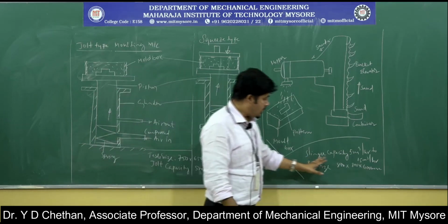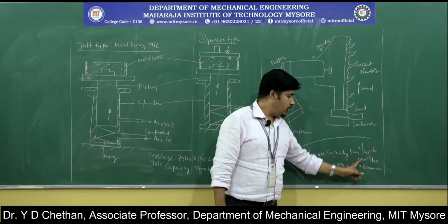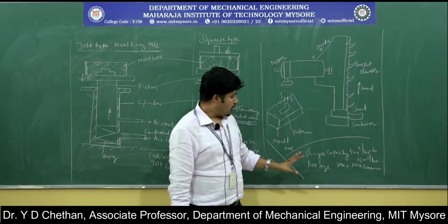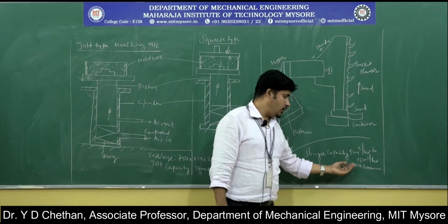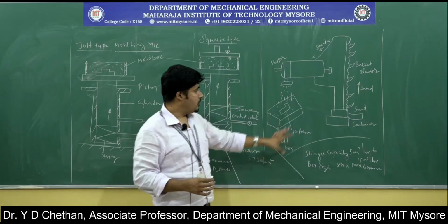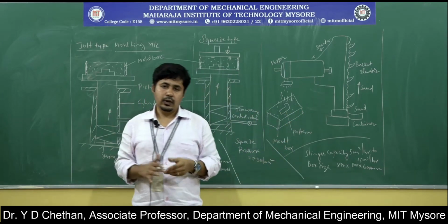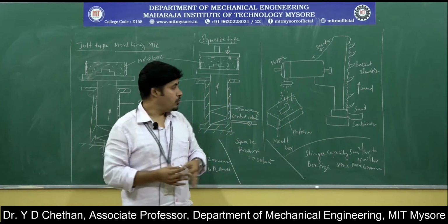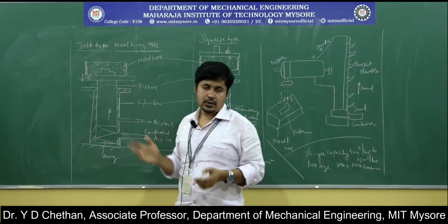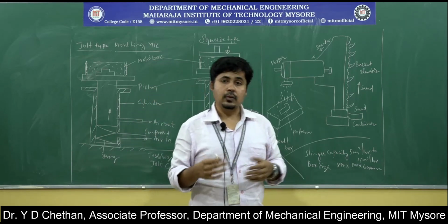The slinger capacity is about 5 cubic meters per hour to 15 cubic meters per hour. That is the capacity of the sand slinger. Then the box size is 800 x 800 x 600 millimeters. This is the specification of the sand slinger machine. If you want a mold with a very big volume, you can prefer the sand slinger machine instead of these two machines. This is the concept of different sand molding techniques, or sand molding machines.